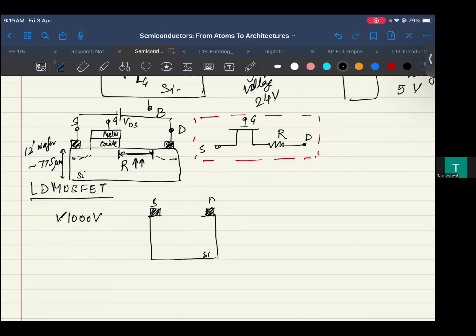So that means you don't have to make the transistor very long in the lateral direction. But what you do is you use the vertical direction. So that means you basically put a trench inside your silicon, right? And when you put this trench, over that you put your oxide, and this metal, right? So this is your metal, which is your gate contact.